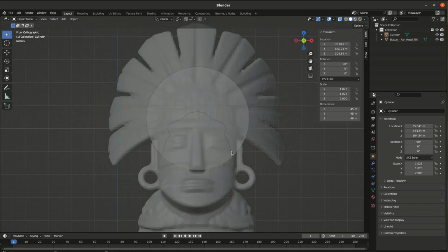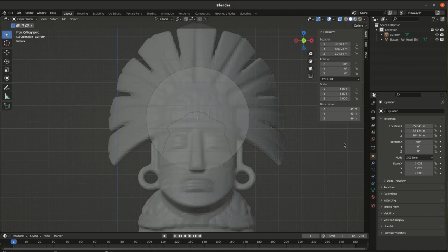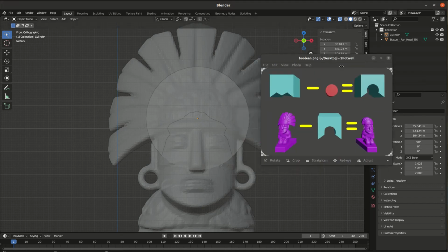Then we go to the front. We have the block properly. So this block is done, the red cylinder. We just need to raise this part around the head, and then we can do the modifier. For this block, we use the plane at the beginning because we need to edit it for the edge to be curly like this. You see, we're going to start with a plane like this, edit the edges like this, and then we need to extrude it to create an object.